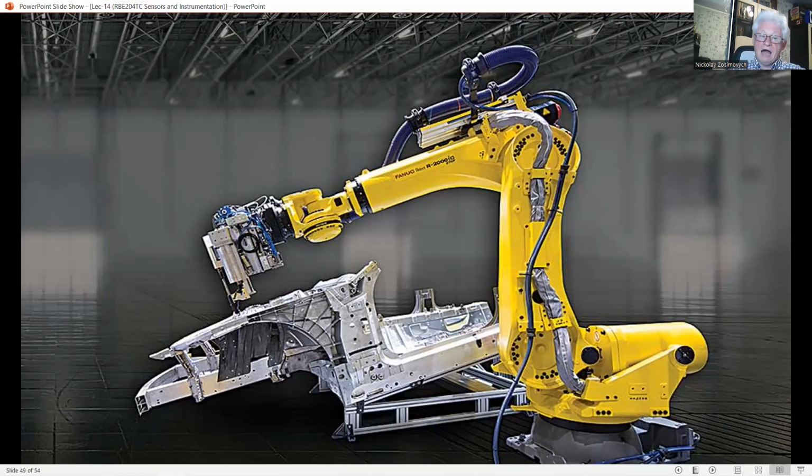For example, activities of the parts handling robot have to be coordinated with the schedule of the forging machine and milling machine. Furthermore, the billets will have to be heated for a specified time, and the machining operation cannot be rushed without compromising the product quality, failure rate, safety, and so forth.